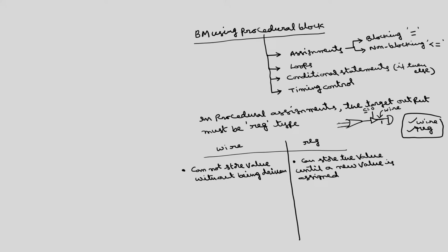The control signal being 1 or 0 depends upon the logic. If I use negative logic, control signal 0 gives output equal to input, and control signal 1 puts the buffer in the tri-state. Suppose I make C equal to 1, the wire will not hold the previous value 1. So, this can store the value only when it is driven. It cannot store the value without being driven.